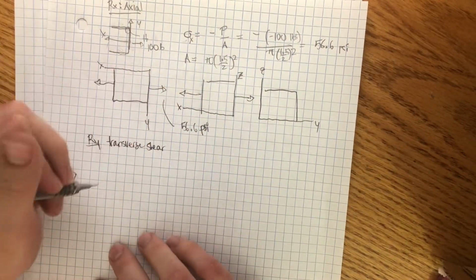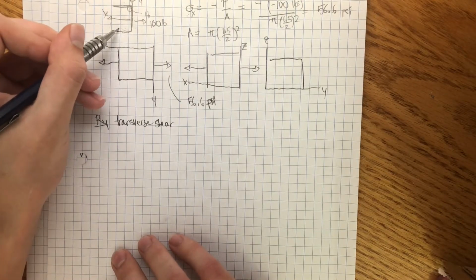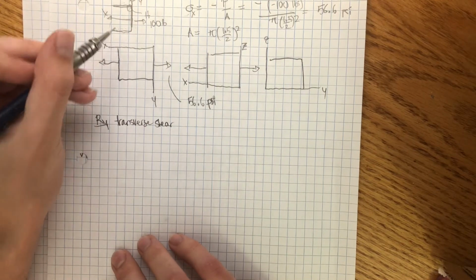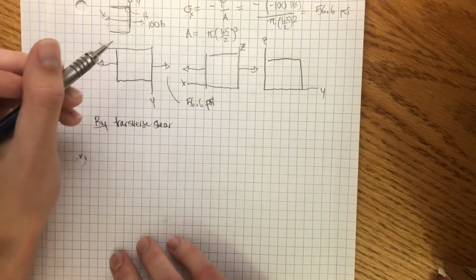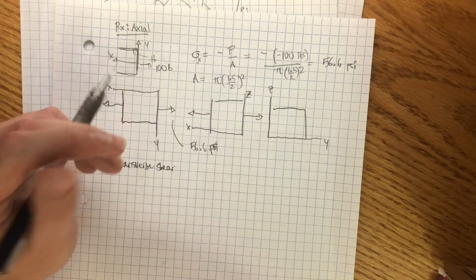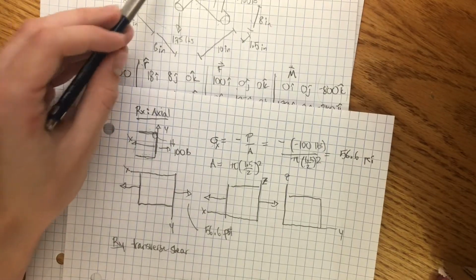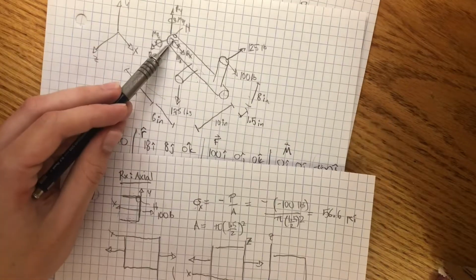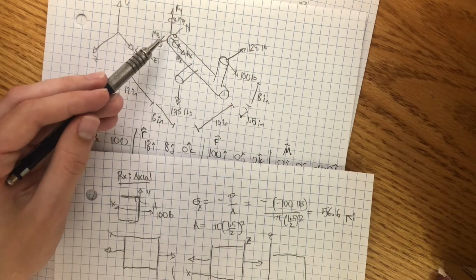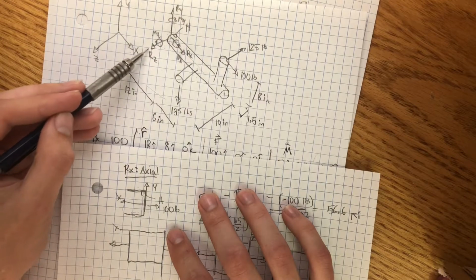we can look at our little cross-section thing from a lateral direction, much like this one, but unlike with this one, we need to make sure we're not looking at it from the direction that the force is acting in. So in this case, Ry is acting in the y direction, if that's visible there. So that means that we need to look at it on the xy plane from the z direction, right?